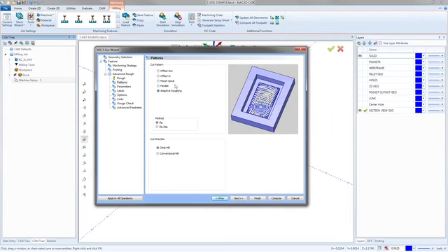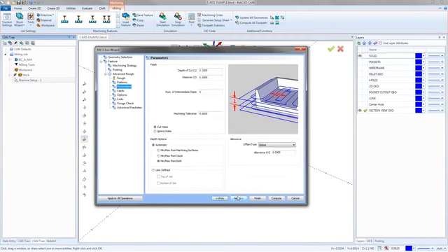With the offset pocket out, I usually treat it more like a traditional job. So I'll set up a decent depth of cut, a decent step over, but I'm not going too aggressive in any direction. So in my case, I'm going to go 50% of the tool. 1/4 inch depth, 1/4 inch step over. The only problem with leaving geometry like this with these big steps is the finish tool needs to come in and clean up these big old honking steps.